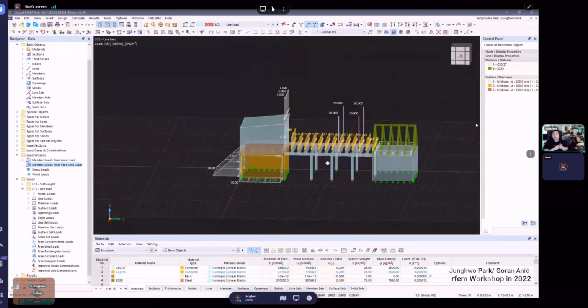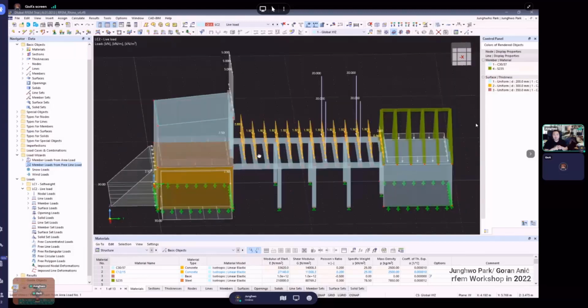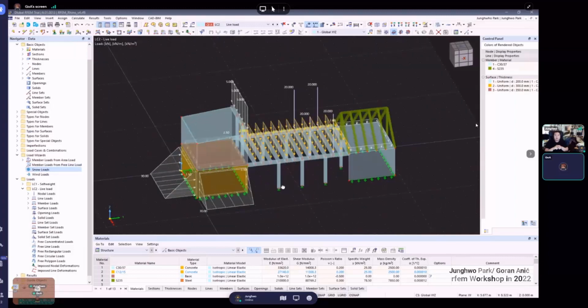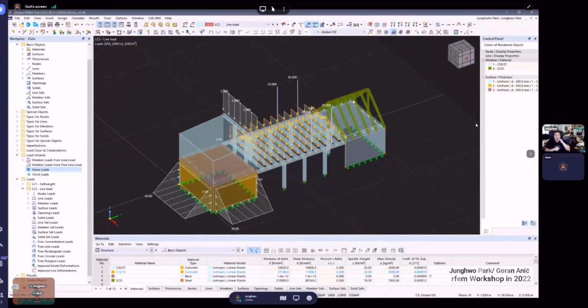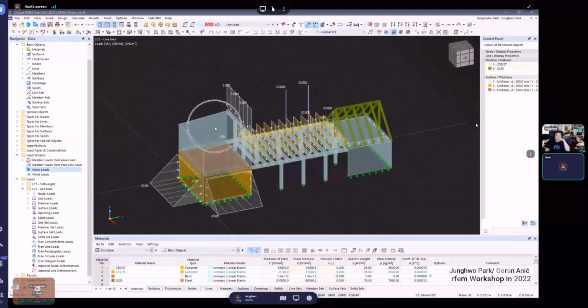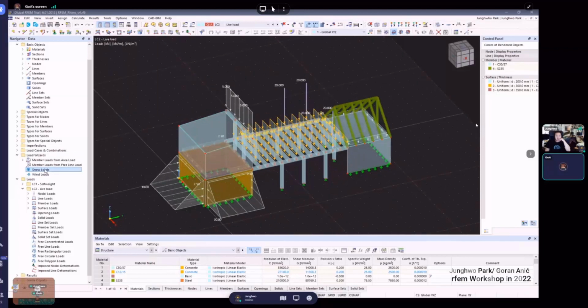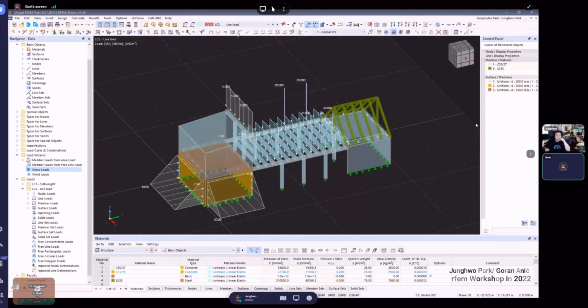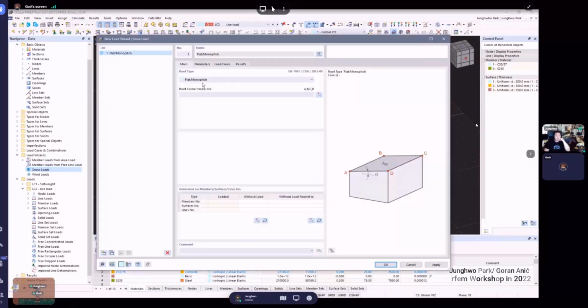What about the load on the concrete roof? If you want to give snow load, you use the wizard also. So here we created two kinds of roof. For example, here is the monopitch roof, or how it's called, monolithic concrete, one slope, and here is a double sided roof. So we can go to the snow option to see what we can choose. This wizard is very nice.